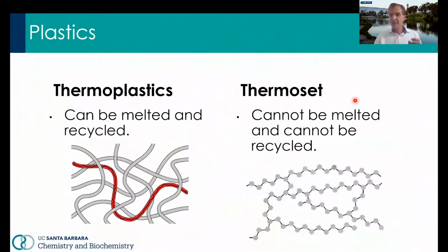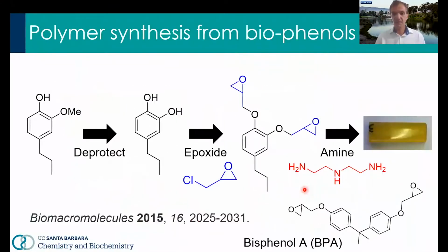I mentioned that the phenol products, besides being able to introduce them as drop-in into aromatic chemicals that are used today from petrochemicals, these phenols are very valuable and they can be used to make thermoset. So there are two kinds of plastics, thermoplastics like polyethylene or polypropylene that have very large entanglement. And there are thermoset that we usually use phenol and bisphenol A, and we do cross-linking chemistry to make very rigid structural materials.